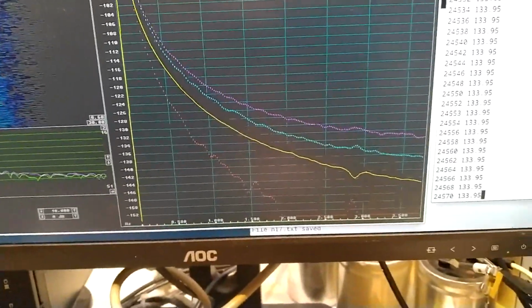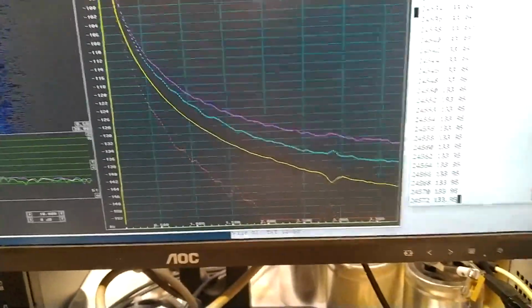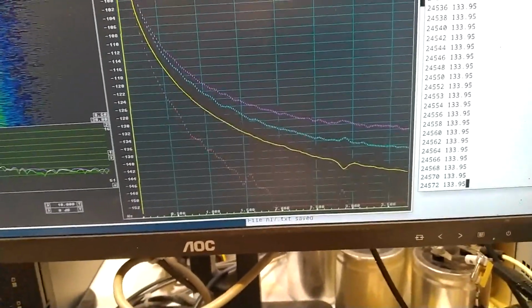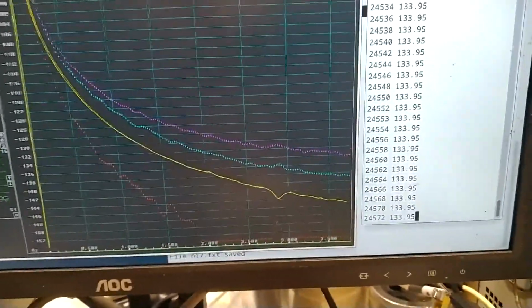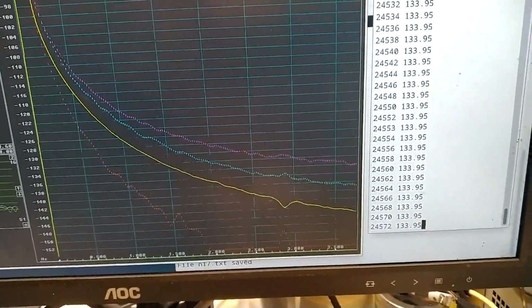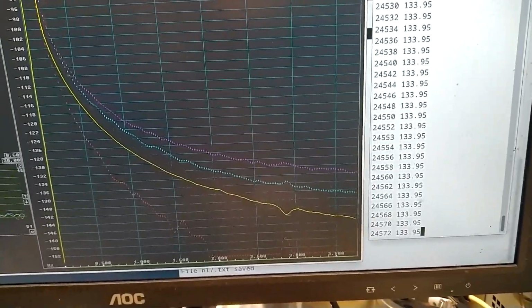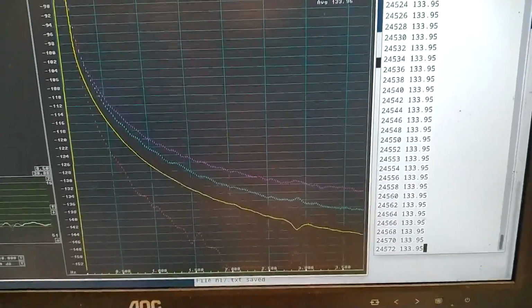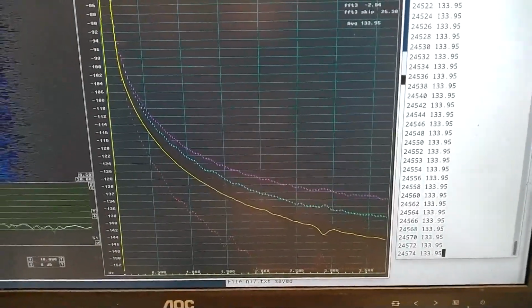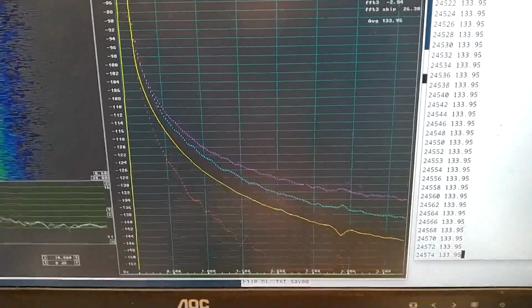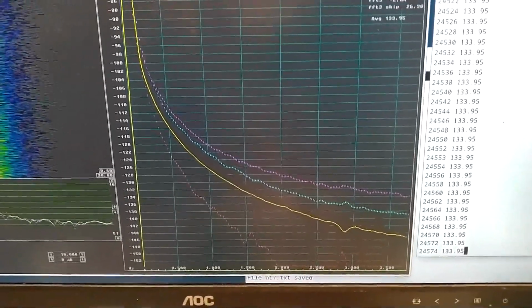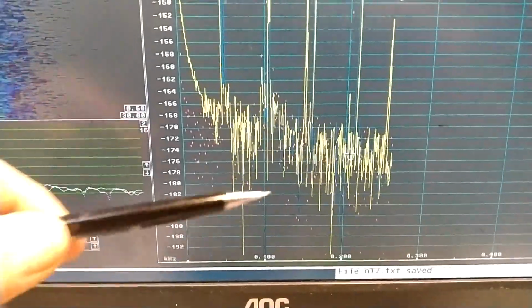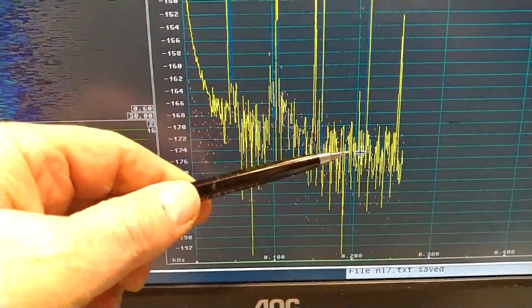The average from 0.22 Hz up to 3.7 is stable at slightly below minus 134. That's what I have seen before. It seems the oscillator has recovered from whatever happened with the crystal. Despite the long time, I cannot really see the noise at 200 Hz offset.